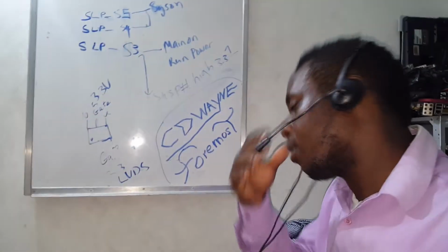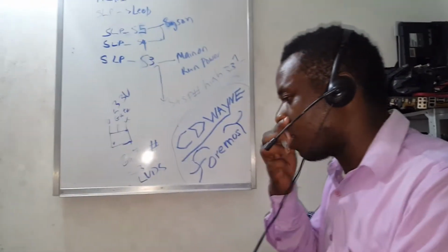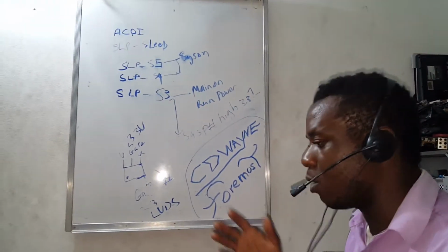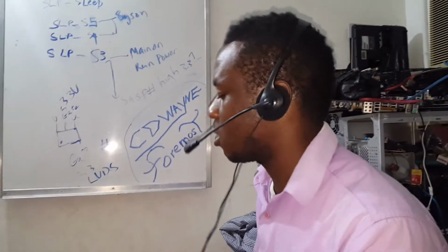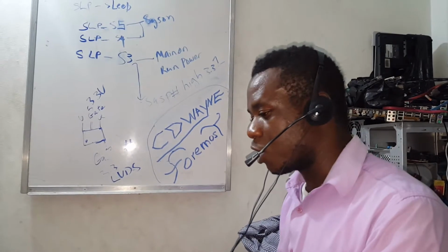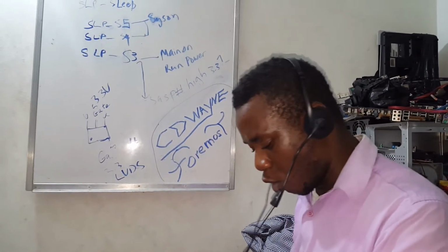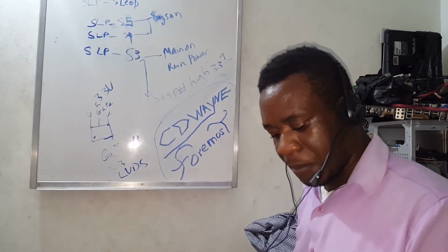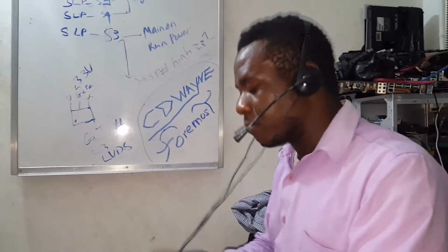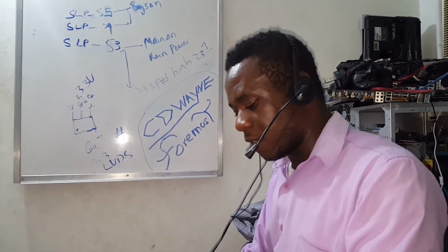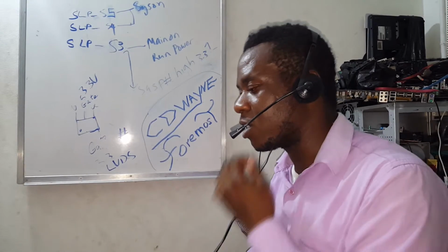And when the battery is full, the IO controller will send the adapter cutoff signal to stop the two input MOSFETs, or the protection isolation MOSFETs, to stop the charge so that the battery will discharge. And I showed you how to check the MOSFET and how to check the battery MOSFET for discharging and when it's charging.